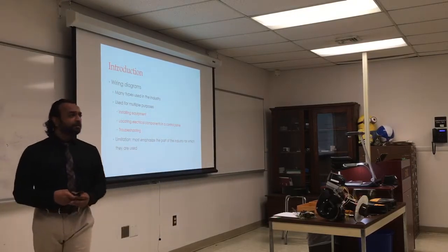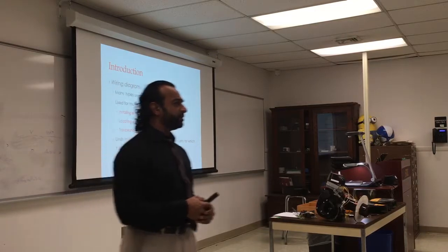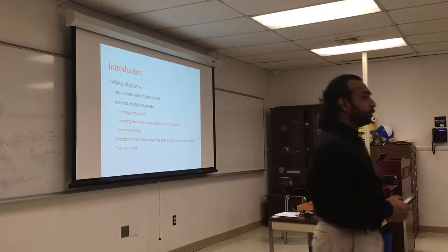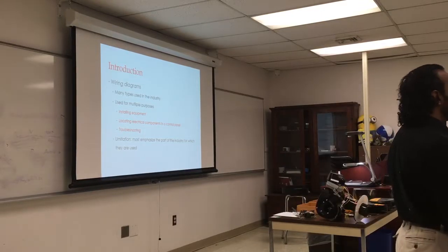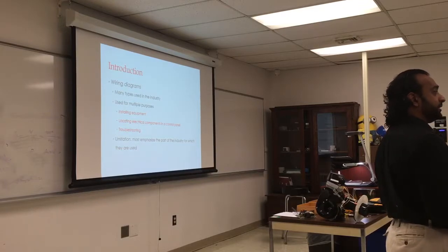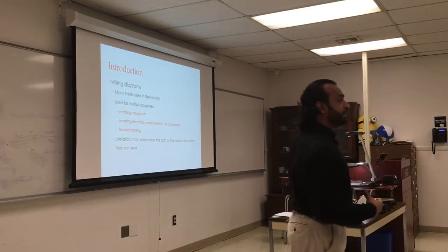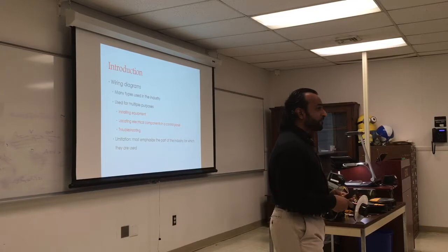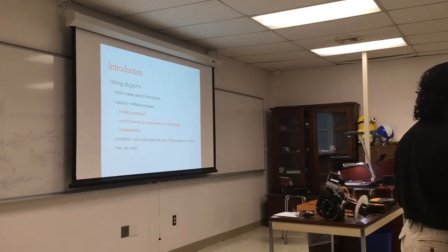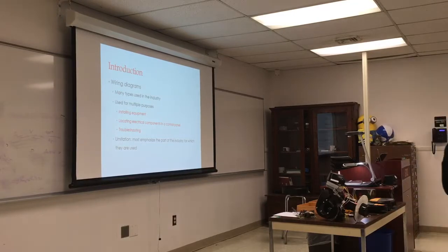Limitations: again, those symbols are different from one industry to another. If somebody is troubleshooting an electronic board, they have different kinds of symbols and different kinds of wiring diagrams. So for our intended purposes, we only use the installation diagram or a ladder diagram. Over time, you will develop a sense of knowing how things connect, and probably within a couple of months working in the field, you don't even need the diagram. You already know where everything should go.